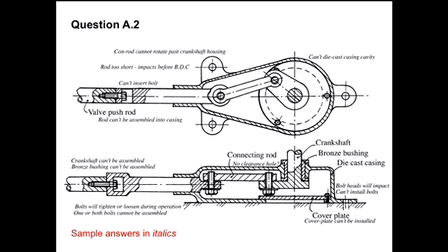There's another one, and that is that this all looks very nice here, where we've got a bolt and we've got this rotating arm, we've got our connecting rod. But as soon as this arm tries to go to about this angle, that point tries to get to there, this bit of material is going to start wanting to interfere with that central axis bit of material.